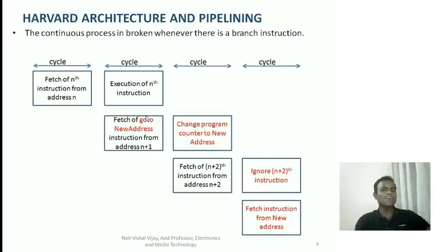There are times when this pipeline, or instruction queue, will be interrupted, and those are the times when you have an interrupt. Whenever an interrupt happens, the program counter, which holds the address of the next memory location from where to fetch the program code, has to dump its address to a stack, and it has to take a new address from where the program code has to be accessed. In such an event, your instruction pipeline will actually reboot, or it will dump the queue.